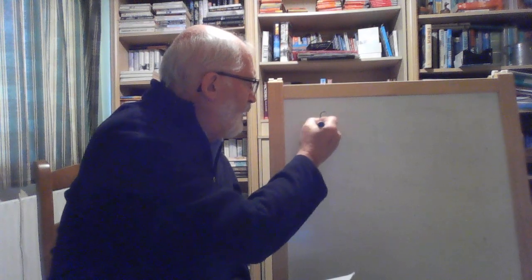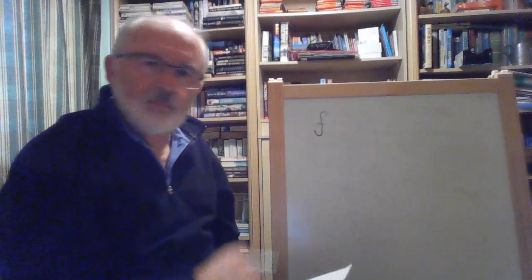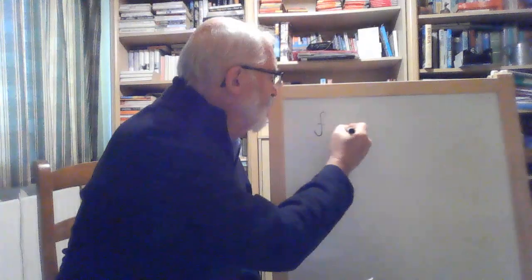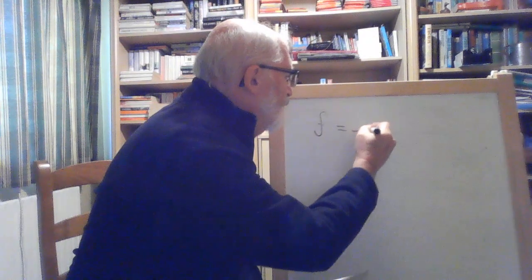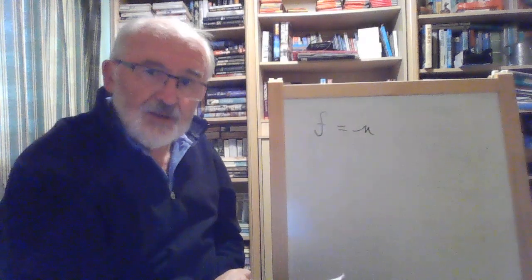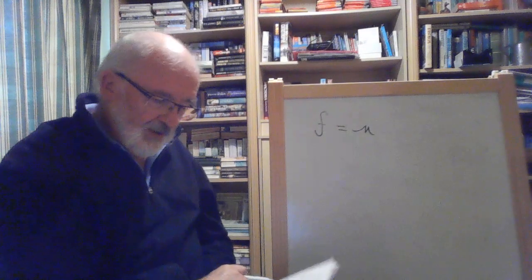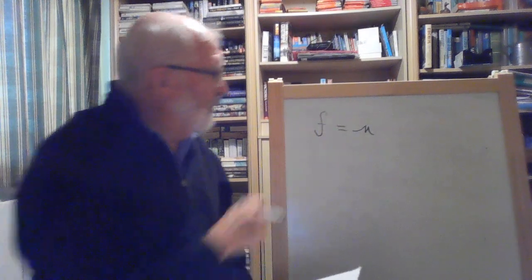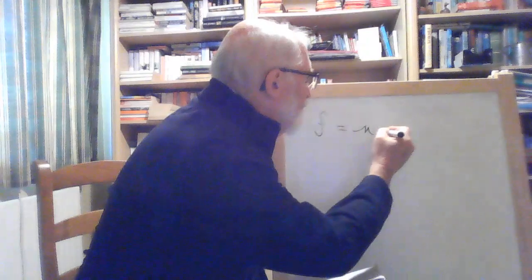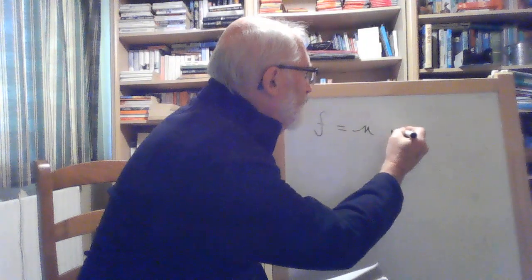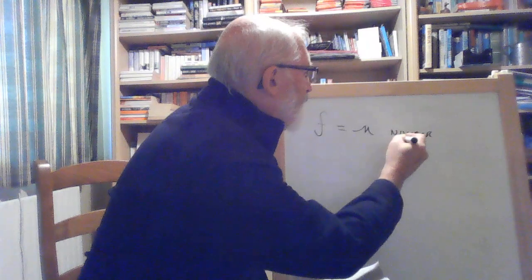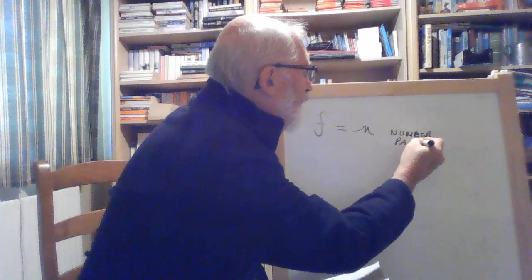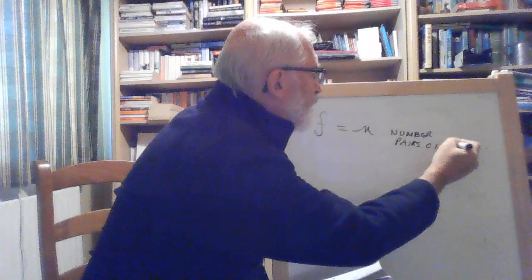And the frequency is equal to, again, the speed of the prime mover in revs per second and the number of pairs of poles on the rotor.